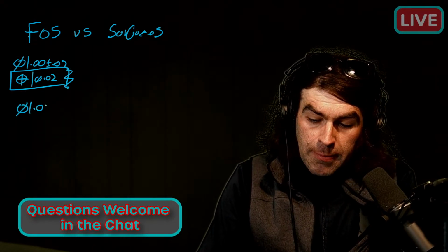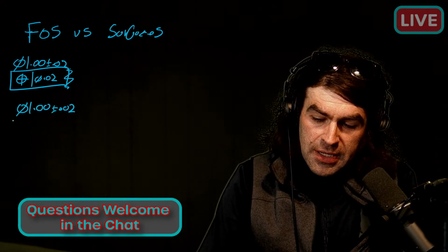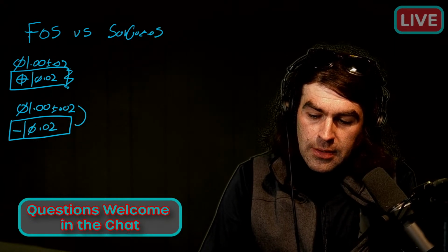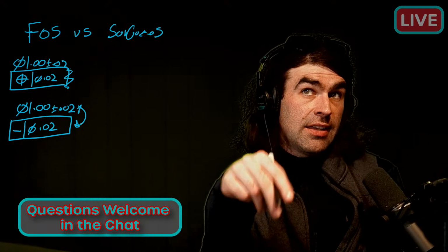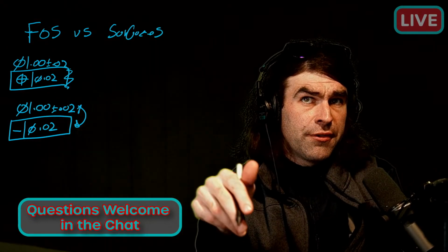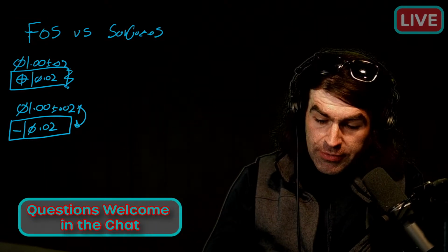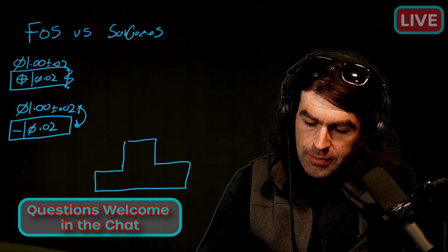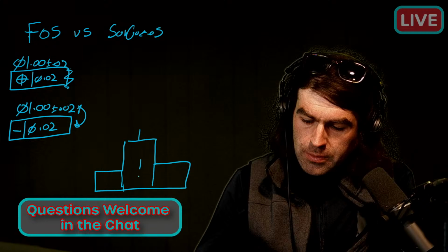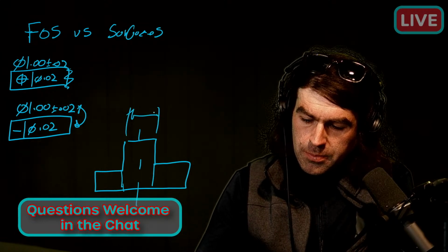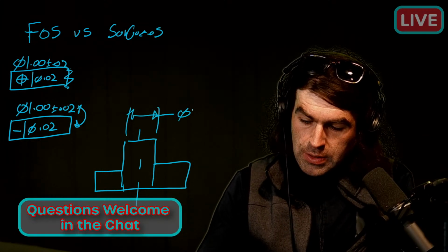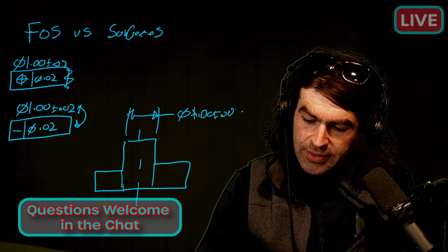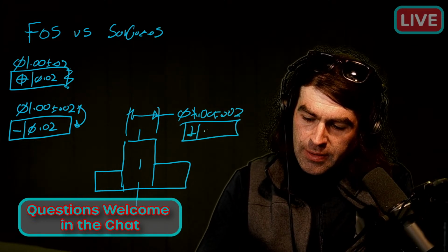Even if we're applying derived median line straightness, we're going to put it with the dimension. And that's a giveaway that it applies to a feature of size. It becomes even more important. Say we've got a pin pressed into a plate, and this is kind of the classic thing for explaining perpendicularity, right?